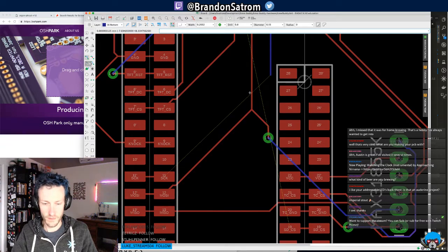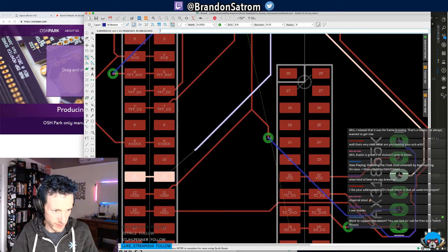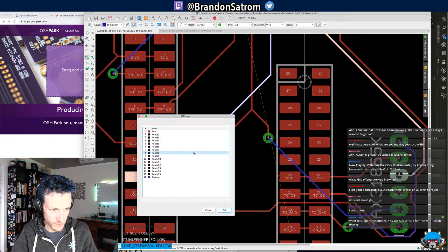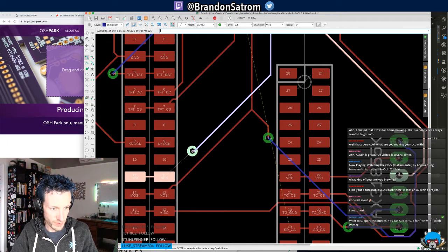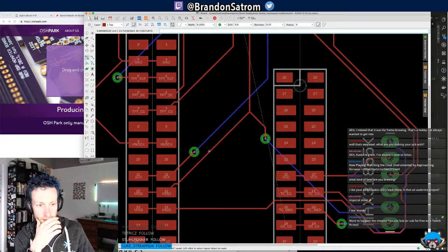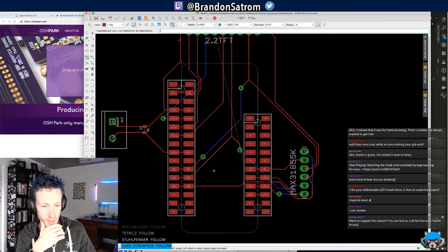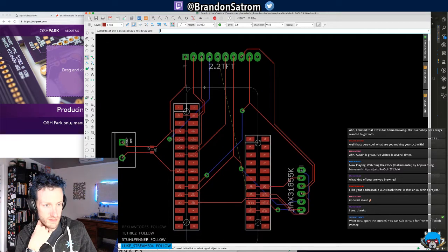For those of you that just jumped on, I discovered that Eagle is ticking me off today with some of the things they did to change the way you do vias to run routes between the bottoms and the tops of boards. So I'm trying to get this done. Okay, we're now down to the very last wire. I will do a little outline and then throw this into OSH Park so that y'all can see. And I think that will be the end. That'll be how we wrap up the stream.